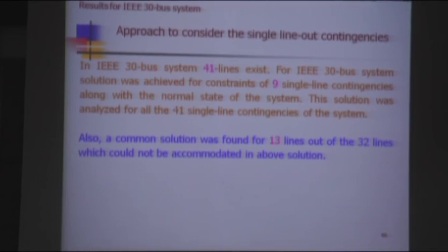That means the remaining relays still have to act as per the protection philosophy. But when that particular part is isolated, the load current and the fault current will change, because those three lines were creating an additional resistance and reactance in the line, and the calculation of settings was based on the whole system in operation. Now three lines have gone out, so the protection quality is degraded.